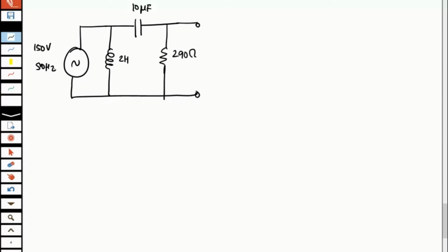Now, in the very first step, theoretically speaking, how can you write V in, the input voltage that you are giving, in the form of a phasor? Angle 0 degree, right? So theoretically, everything here is theoretical, so what will mod V in be? This value. This will come out to be approximately 107.14. Please calculate this yourself, and this will be your theoretical value of V in.